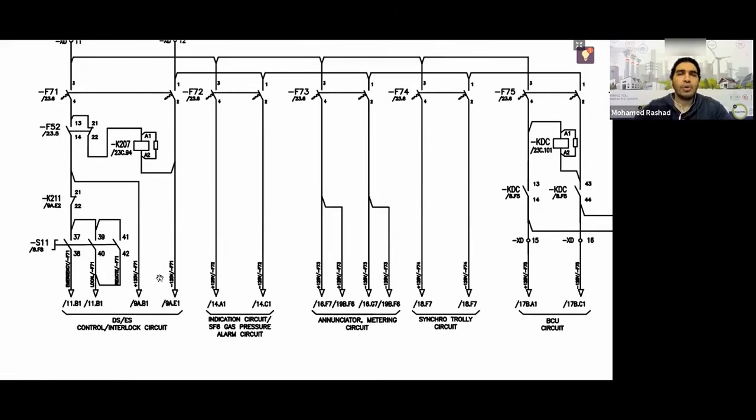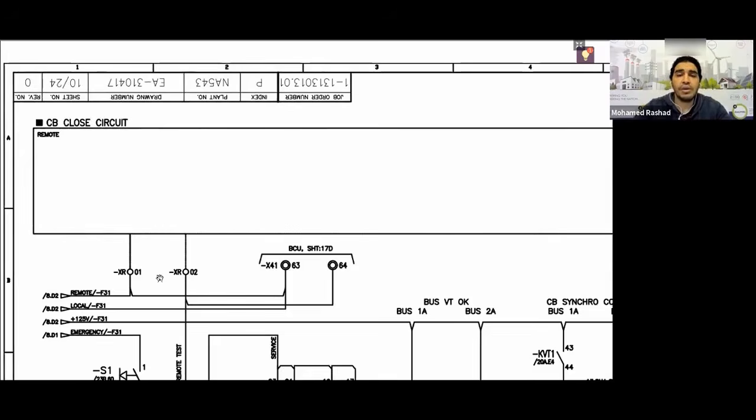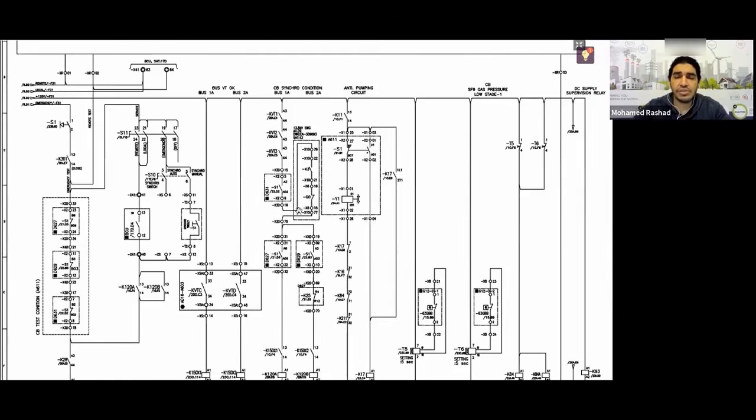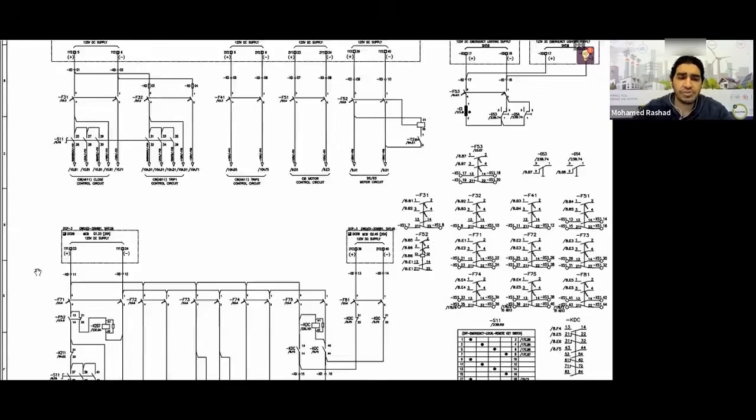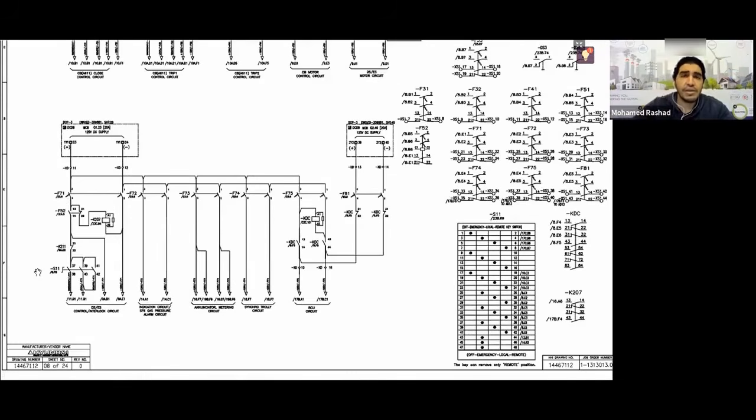You might say, oh God, so now I'm going to control the interlock even for the breaker through this circuit. I would tell you, no, the breaker's interlock is found within the control circuit of the breaker itself, right or wrong? When we were explaining here, the closing circuit of the breaker itself had all the interlocking conditions specific to the circuit breaker. However, in the case of the disconnector air switch, its interlocking must have its circuit stored from the same DC that is specific to its control.